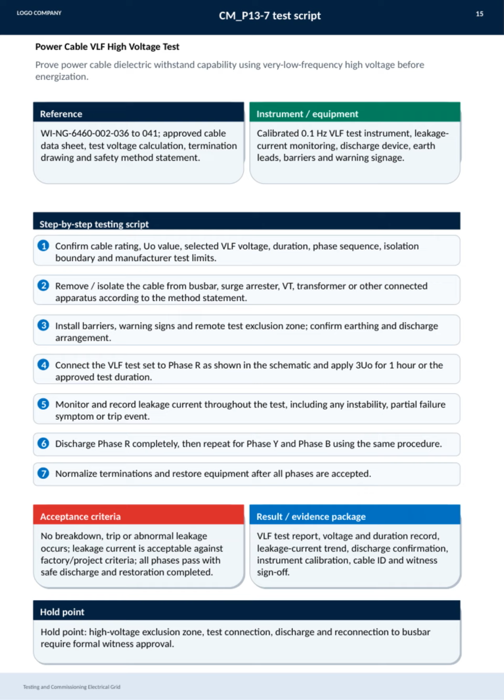Our documentation includes the VLF test report, voltage and time records, leakage current trends, discharge confirmations, instrument calibration certificates, cable identification, and witness sign-off. Finally, remember the hold points. Establishing a high-voltage exclusion zone, test connections, discharges, and reconnections must all have formal witness approval to ensure safety and